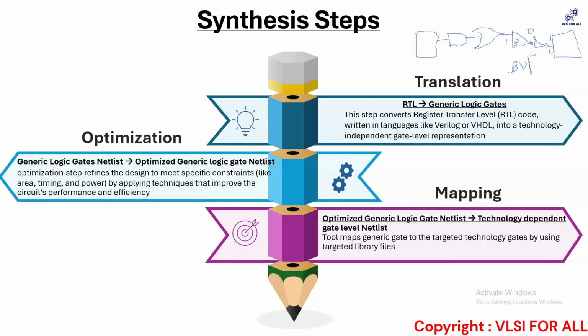There is no constraint that you cannot, at the end you can even do a LEC between the RTL and after the routing netlist as well. Okay, but the only thing is that it takes a lot of hours to do it. Okay, this is not a very simple process where you can get the result quickly. For a complex design, it takes 8 hours, 10 hours, 12 hours.